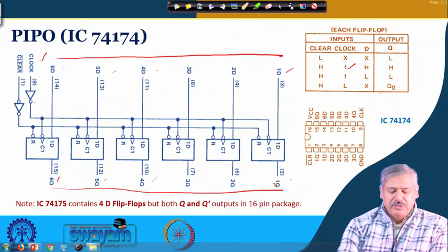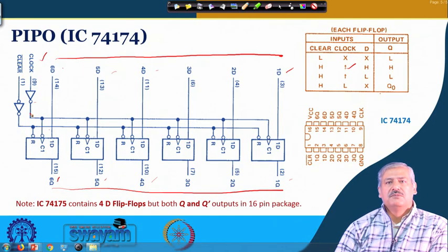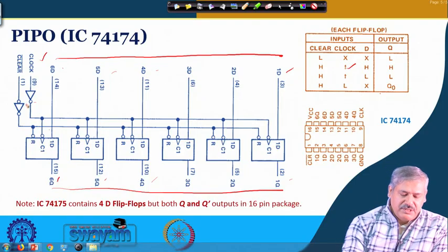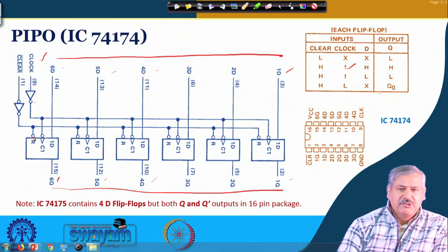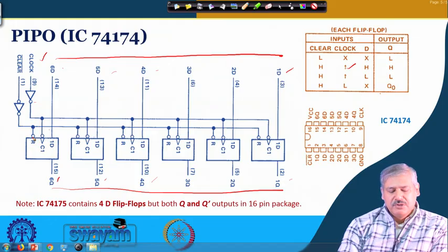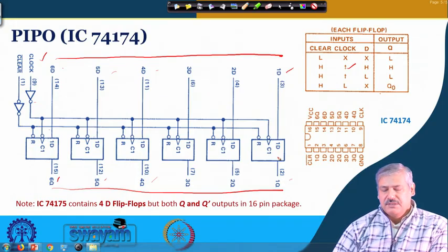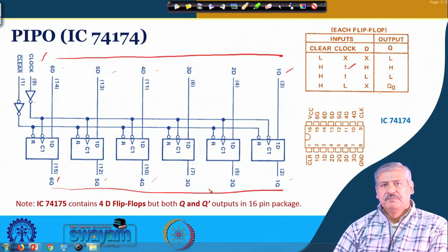And if you want to reset or clear it, you can do all the flip-flops together. So, it is a common clear. There are 2 bubbles here and then a bubble, so basically it is active low. If you put a 0, irrespective of the other values, it will become reset.